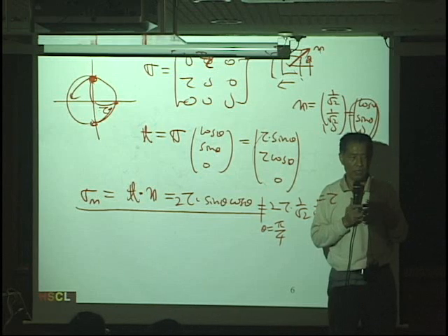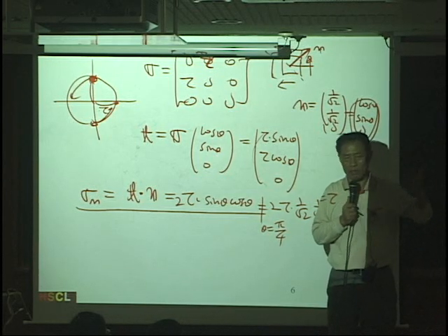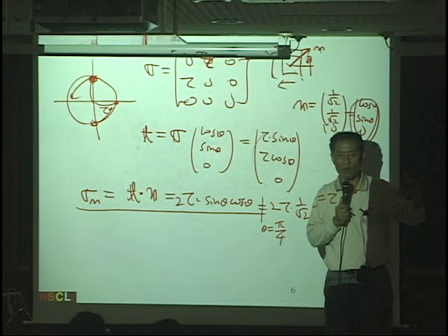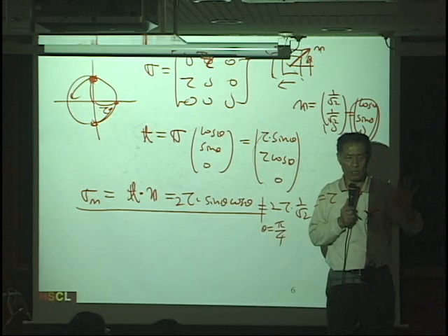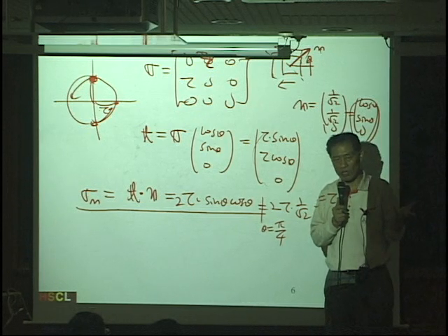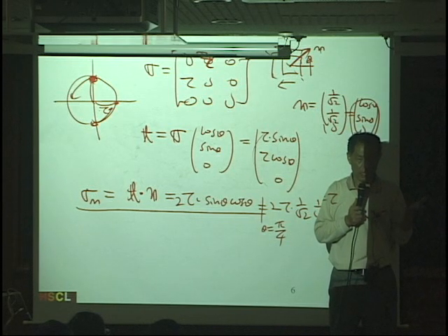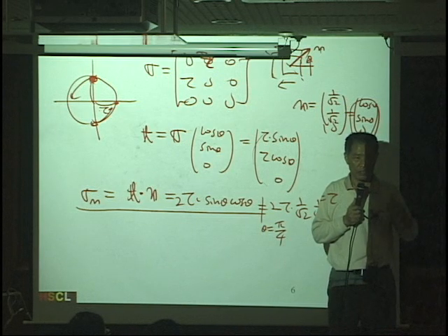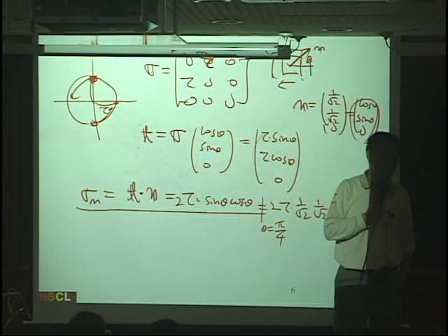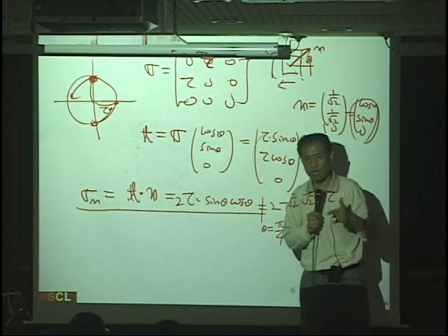Especially when there is a certain geometric constraint in the x direction or y direction, whatever direction. If we have a geometric constraint, meaning a constraint on strain, right? If it's free, the stress will be 0. If constrained, then the strain will be 0.